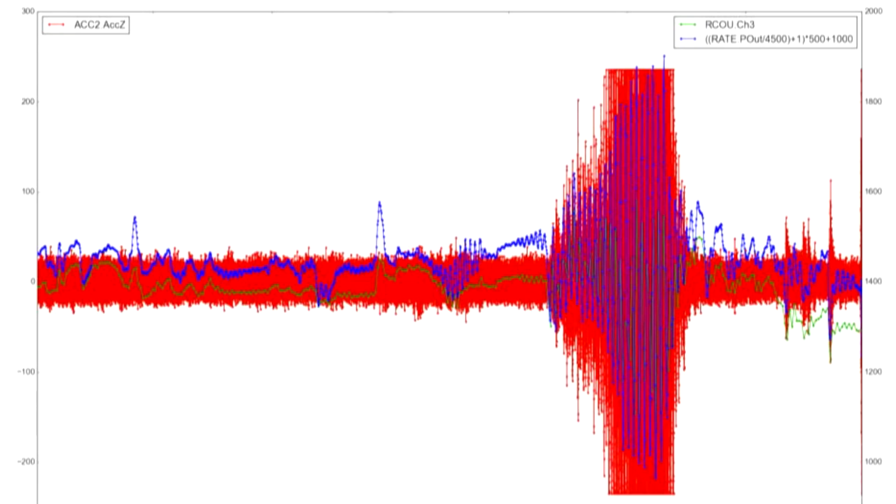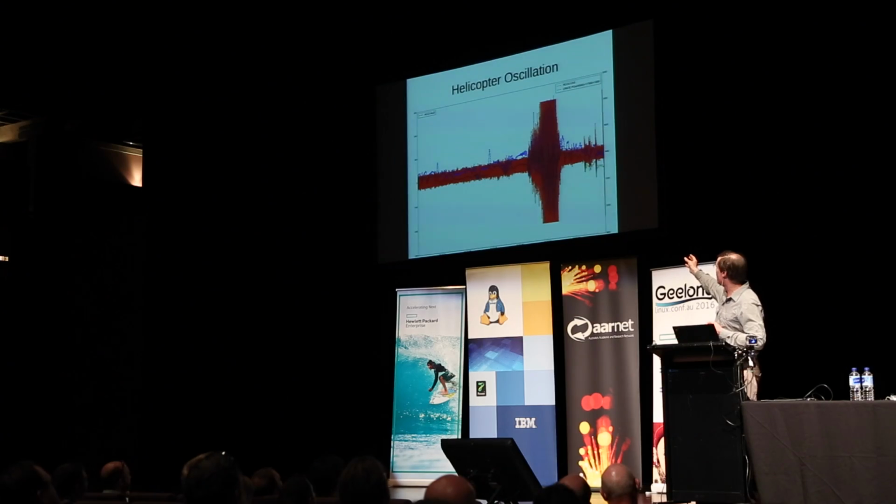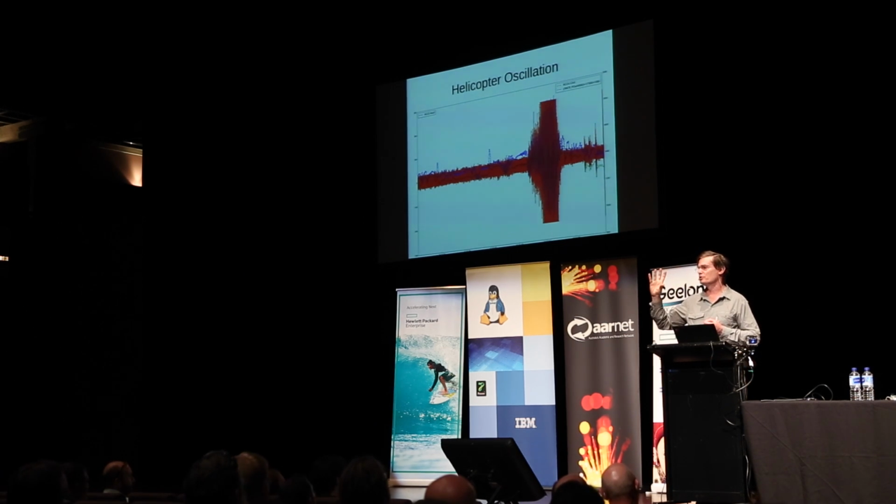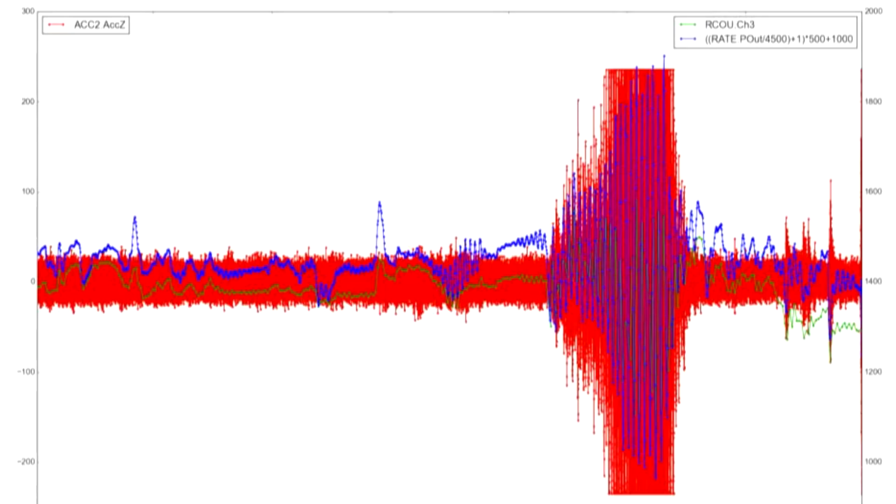And you may notice there's this little part of the graph there which you never want to see in a flight log of a model aircraft, which is a very flat top. And you can guess what number that is. That's 24G. And so the aircraft, in the space of a couple of seconds, went from 6G of vibration up to saturated 24G, and probably extrapolating it was more like 30, 35G, something like that. Peak to peak, it's more like 70G. So that's a lot of vibration.